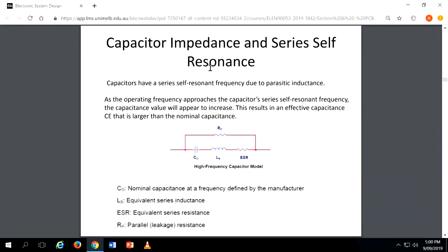That is the reason in the previous circuit you have seen after a couple of megahertz the inductor is taking over. But in your DSO you will not see any of these effects. So that's the reason we are teaching you, except your ground you should be isolating. But these types of responses you will see when you are designing at high frequencies. Your DSO, you might think that it is high frequency, but it is not at all high frequency. 20 megahertz, people will laugh at you if you say high frequency.